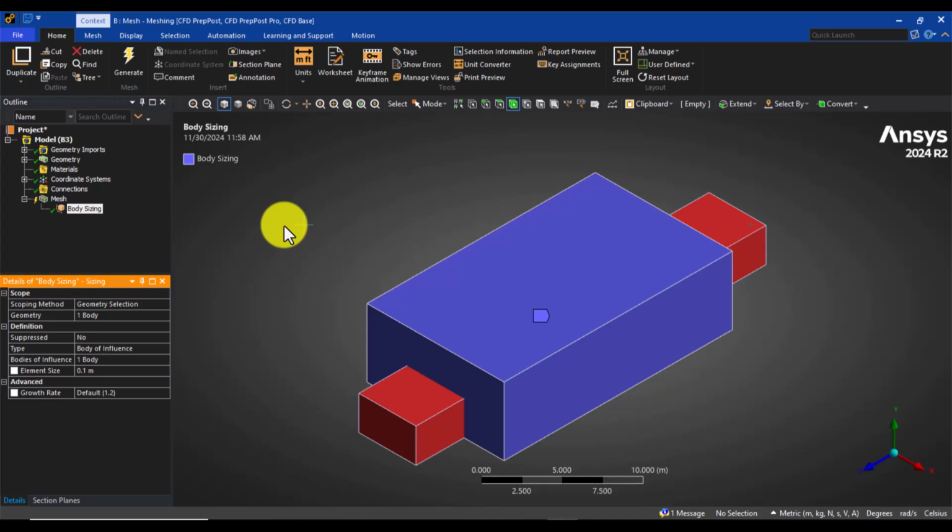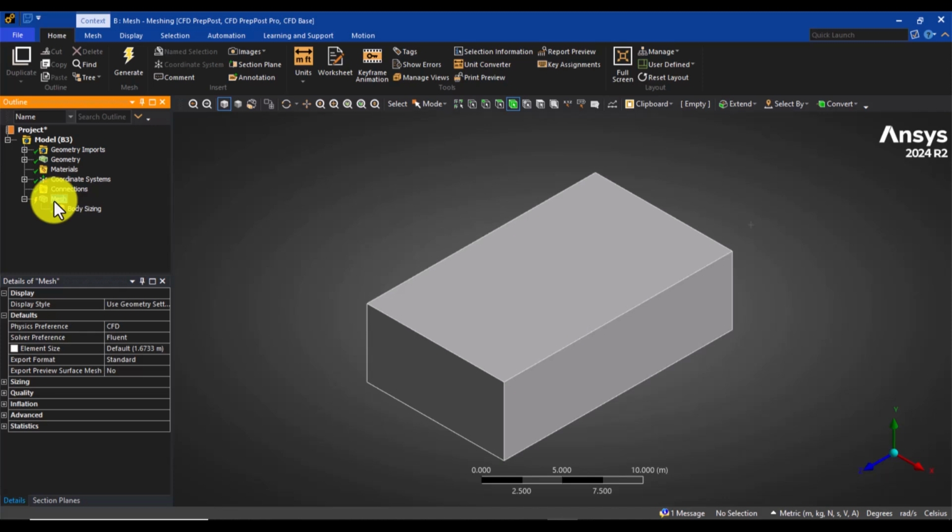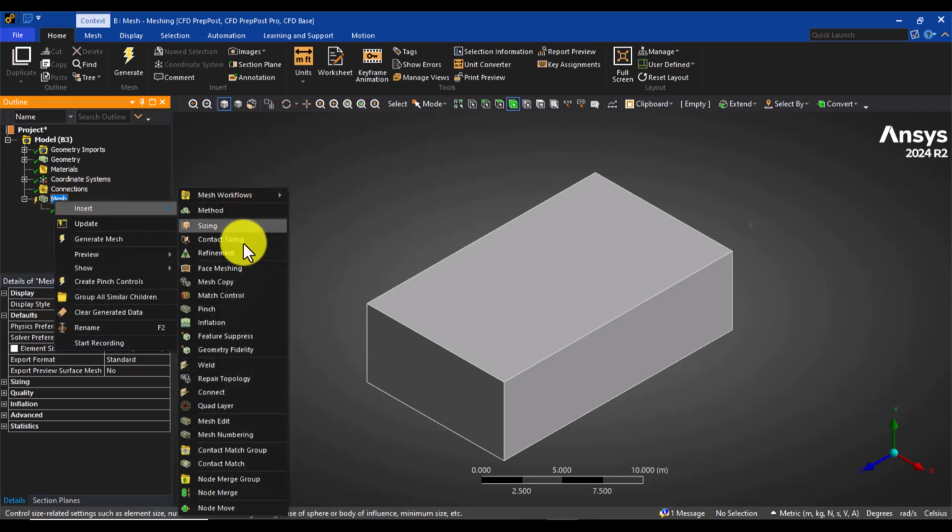Because this is an aerodynamic investigation, the flow separation and wake regions are included. One of the key important regions for us is around the walls. I mean in the vicinity of the ground, beneath the car, and around the car. So this is where we use boundary layers or boundary layer mesh grid. And in order to have that, what you have to do is to once again right-click on mesh, but this time insert inflation.